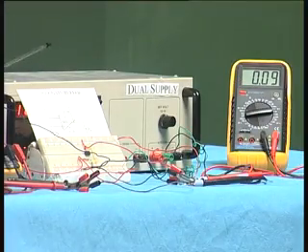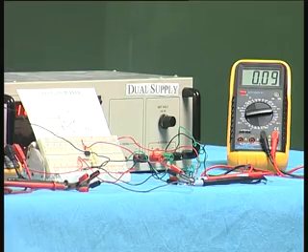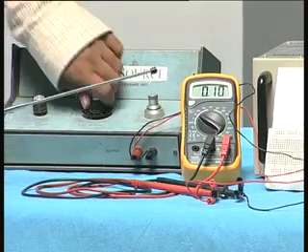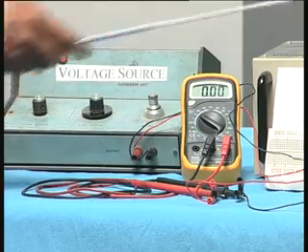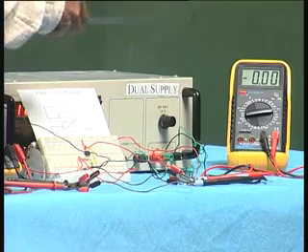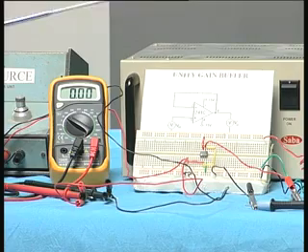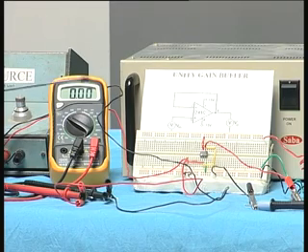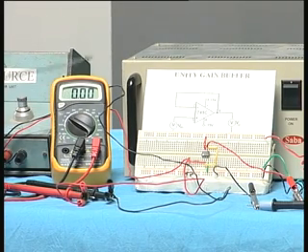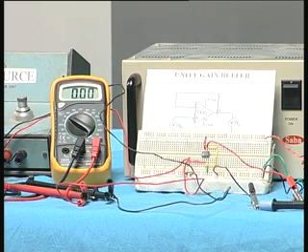Why is it so? That brings us to a very important idea: when I have 0, for example, even though it shows 0, it will still have some small residual voltage which we call offset voltage. Even when the input is 0, there could be a very small offset voltage, and that is the reason why at very low voltages you do not get exactly the same value at the output as the input. We will discuss this offset voltage and other characteristics of the op amp in one of the later lectures.